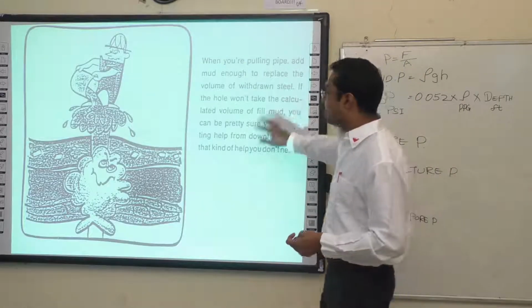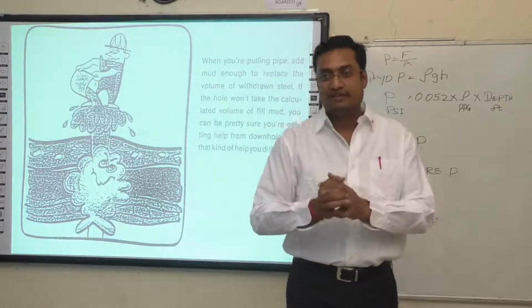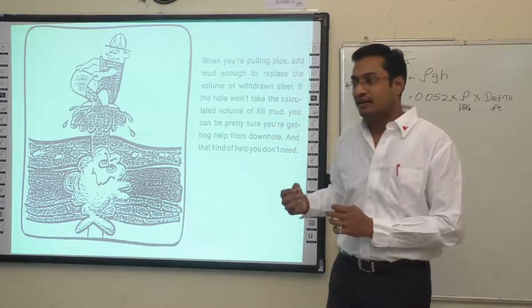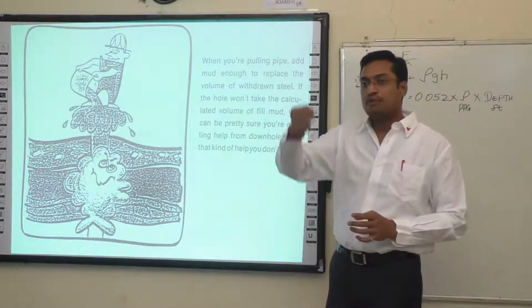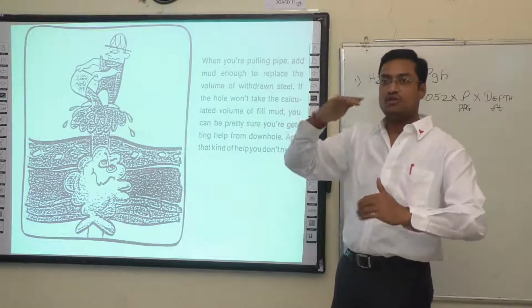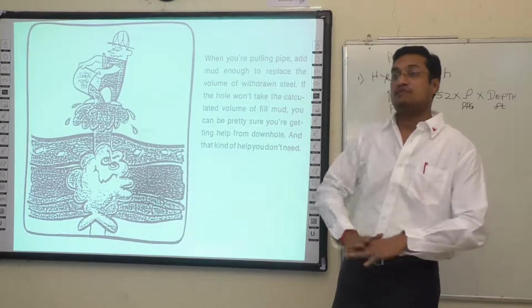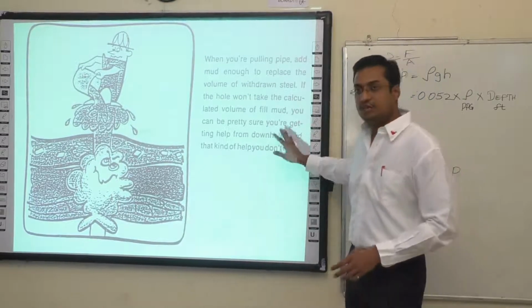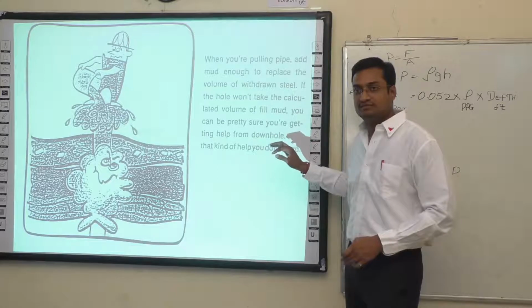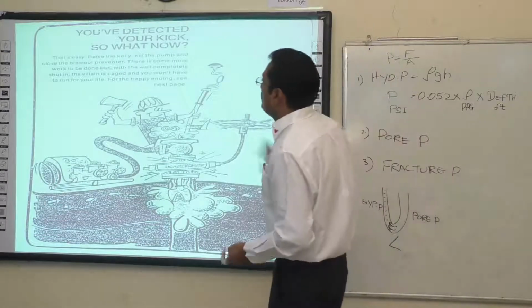When you are pulling the pipe, if you are pulling faster, the swabbing effect can get you into a kick. Every time you start pulling your pipe, you need to keep filling up so that the hole is always full. If the hole is full without filling, or if there are more returns, that means you have taken a kick, with more support from the reservoir. So you have detected a kick.